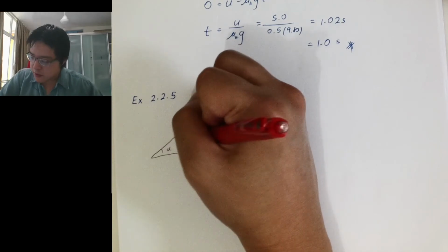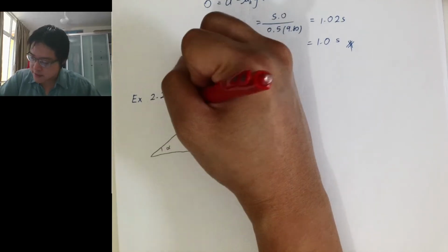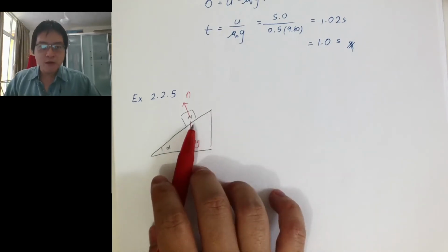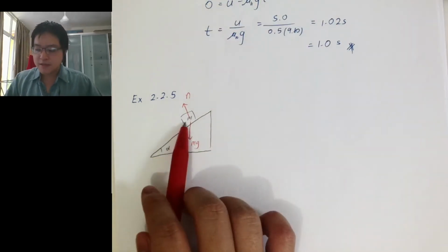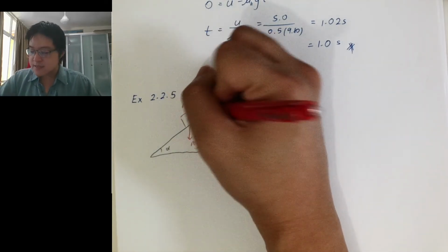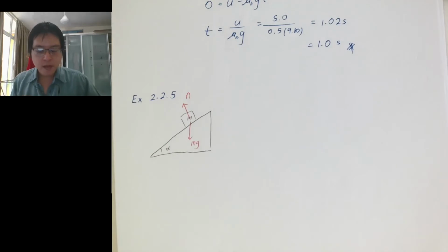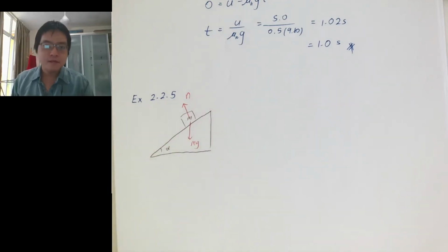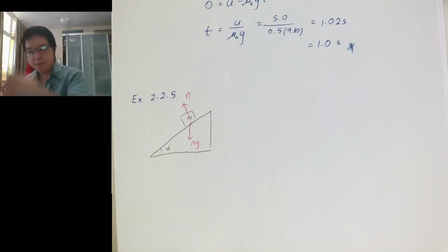Free body diagram: I got the weight. It is sitting on the surface, so I got N over here. And then we want to consider the situation where it doesn't move. The reason it doesn't move is because there exists a static friction. What is the direction that you should draw? Just remember, static friction means whatever direction keeps it fixed.